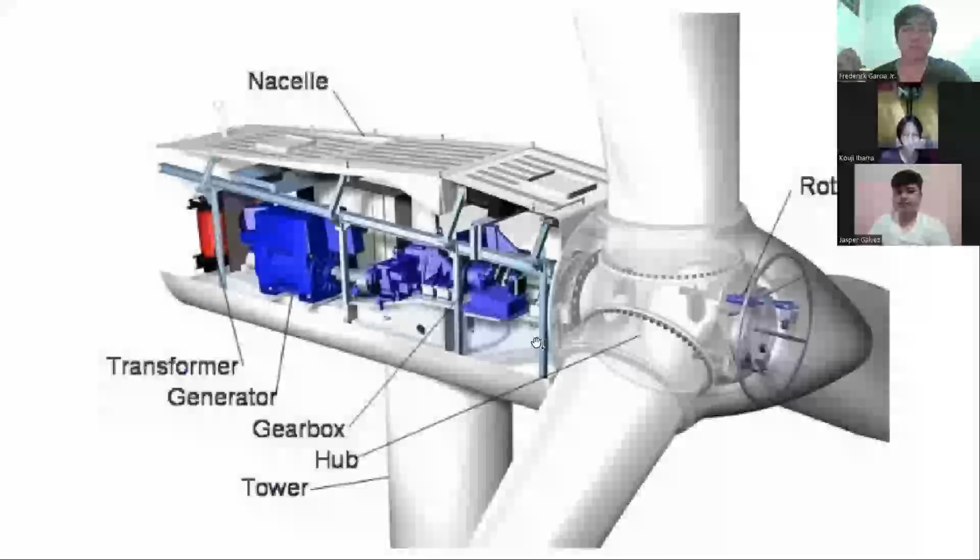Here is a cross-sectional view of a wind turbine. You can see here the main rotor and the blade, which the blade is attached to. It's connected to a gearbox. You've probably seen these things spin very slowly. Thus, we need a gearbox in order for the slow rotation to be converted properly into the fast RPM needed by a generator.